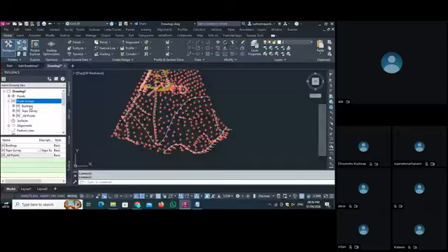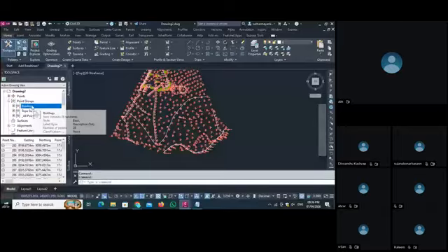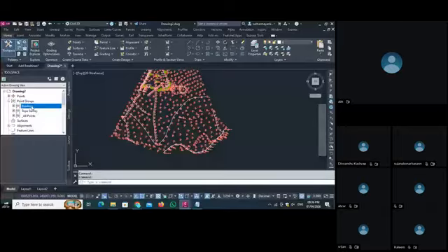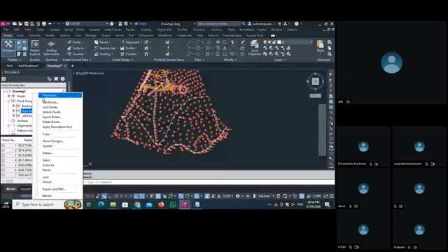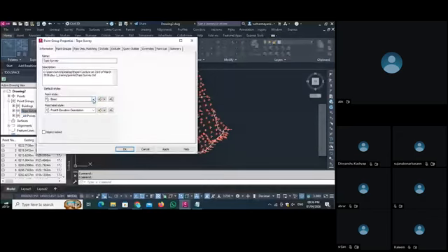So as this is a first step, if you want to see only this group, if you do not want to see the whole set of points, then you can change the style from here. If you set point style to none, and the label style to none, then Apply.